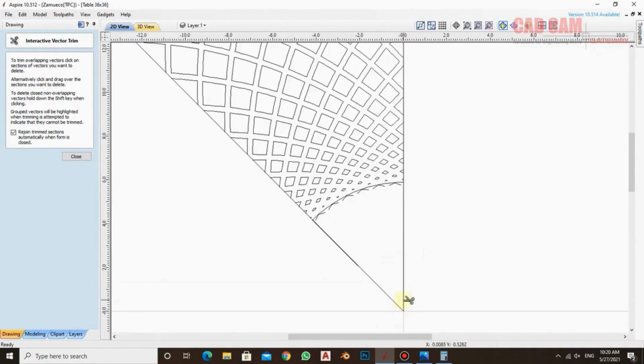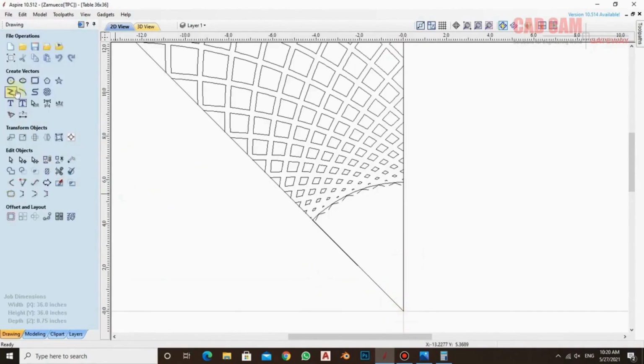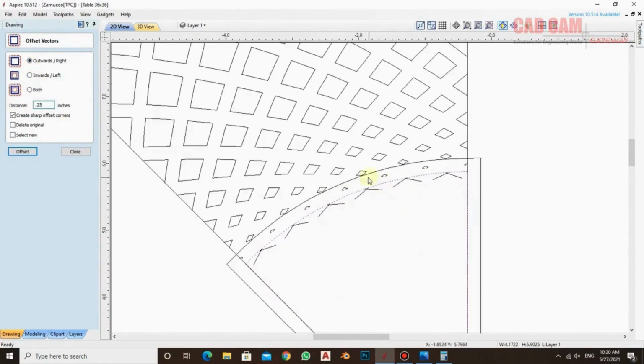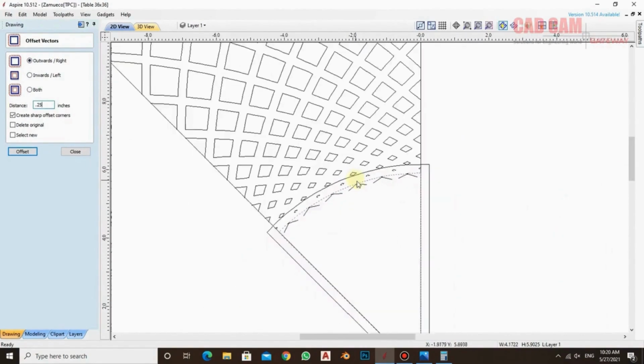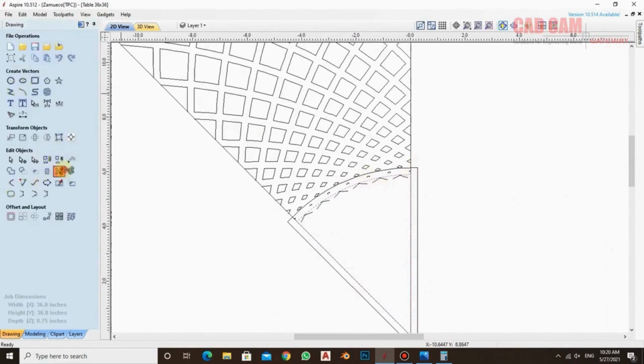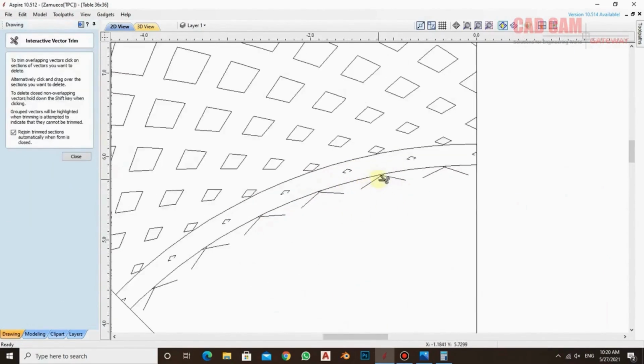Now, the circle we placed here, I'll make it a bit bigger. You can also do this using the offset tool. In this, I will offset this object outward by 0.25. So you can see it will connect with them up to here. I will trim the extra part from here. So I have trimmed this, and also on its side.